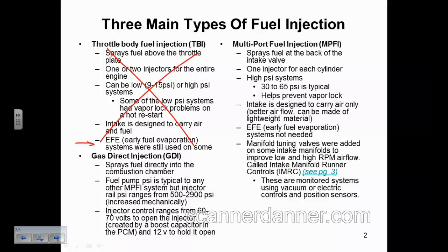And you see that I have some numbers on here that the injector pressure can be as much as 3,000 psi on the tip of the injector. The pumps are similar from what I've been told and what I've read. The pumps in the tanks are similar and pressures are similar. You might be around 100 psi rail pressure. Then we're using a mechanical type pump to raise that pressure. Hydraulics we're using to raise that pressure up to the higher pressure the injector needs.